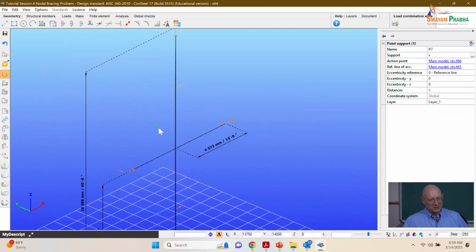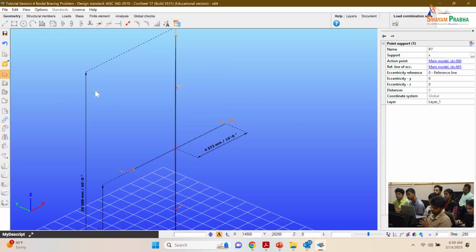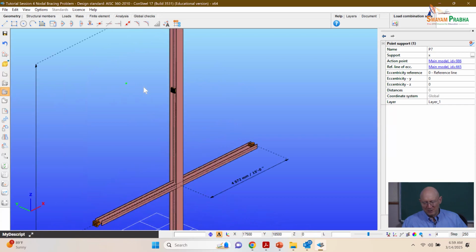So if you basically said what's the unbraced length LY for the column, what would you say it is? The whole thing is 60 feet. It's 15. 15, right? That's right. But if you say, well, what's the LZ? It's 30. 30 feet, right? Everybody good? Okay. So that's our situation here. We'll come back to this view again.